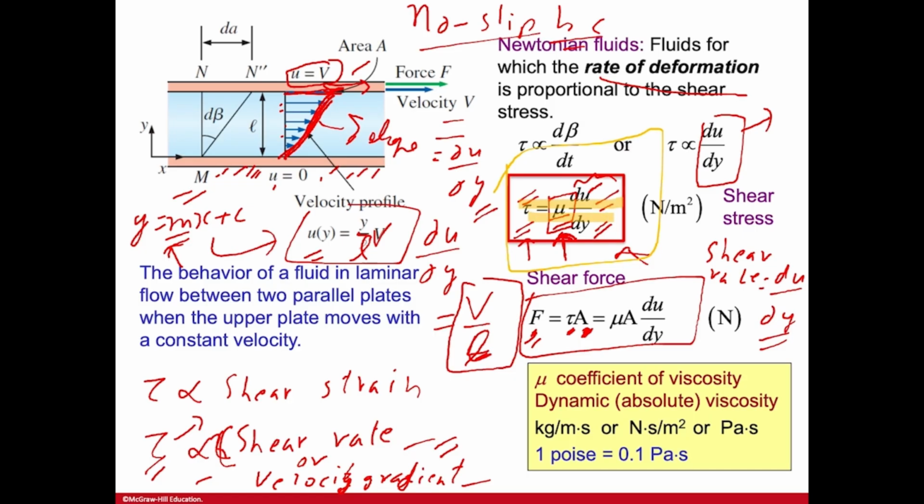This relationship is very important, and it is actually used even in calculating very complex forces or stresses. If you're thinking about the drag force that you compute, for an analytical or textbook problem or for a very complex problem like flow over a rocket or the aerodynamics of a supersonic aircraft, the drag force is essentially a tangential force. The force that constitutes drag is from shear or friction forces because of internal resistance.